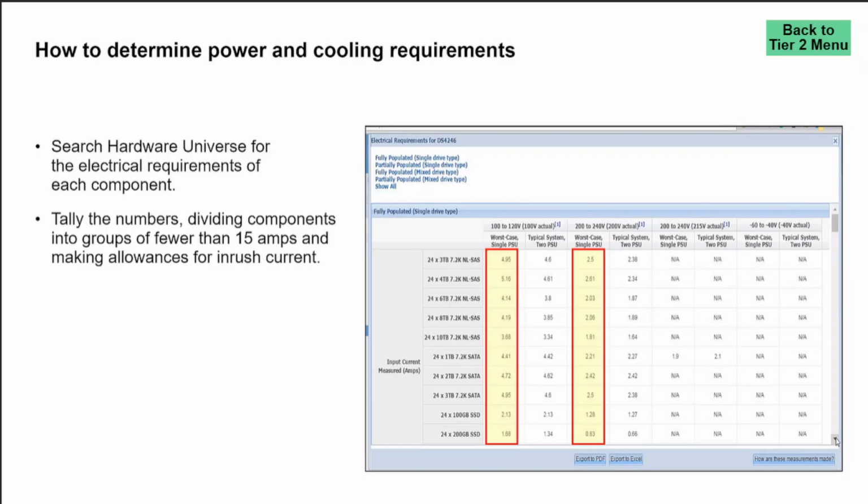Customers with programmable PDUs can further mitigate inrush concerns by programming the outlets that the storage controllers use to wait 5 minutes before turning on. This approach ensures that all drives power on before the controllers boot. If the drives of the root aggregate are not powered on when the storage controller looks for them, then the storage controllers go into a reboot loop trying to find the root aggregate.